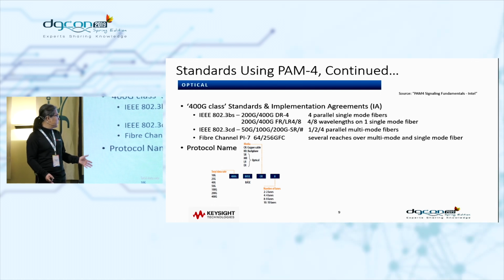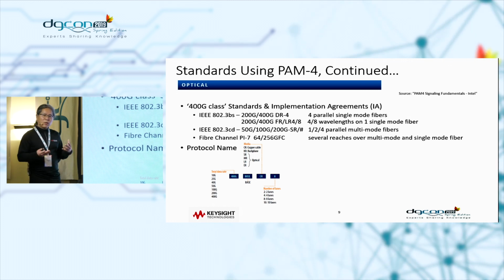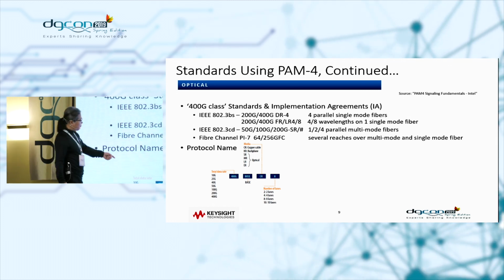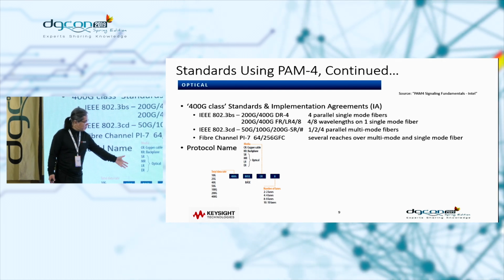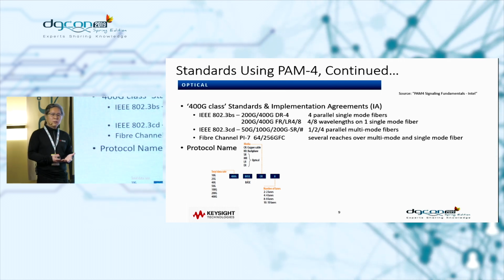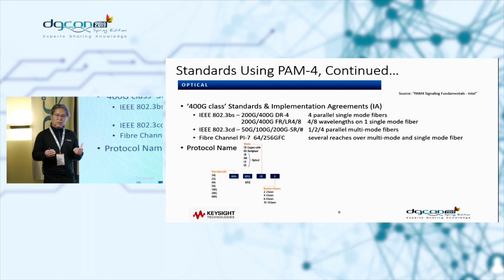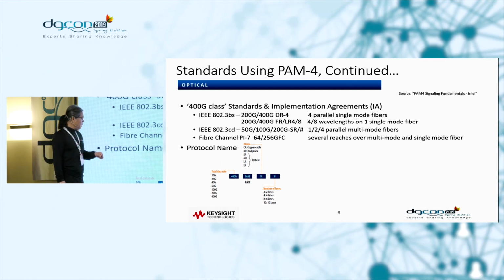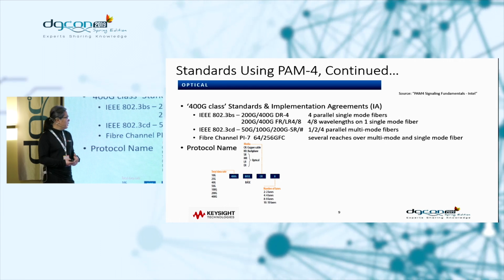So how people are defining the name of the Ethernet, it starts with the total data rate. When people say 400GBASE-CR8, how we interpret it is basically the first number is the total data rate, and second is just BASE. And third one is talking about the medium, all right? So if it says CR, that means the copper cable is used for that transmission medium.